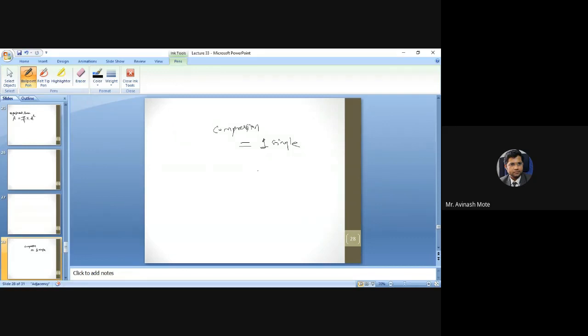What is the problem? If a large size mold is there and 4 components are to be manufactured, through compression molding we cannot ensure that there will be equal pressure on all these 4 cavities. That is the issue. If there is a single product, single cavity, the pressure will be concentrated.